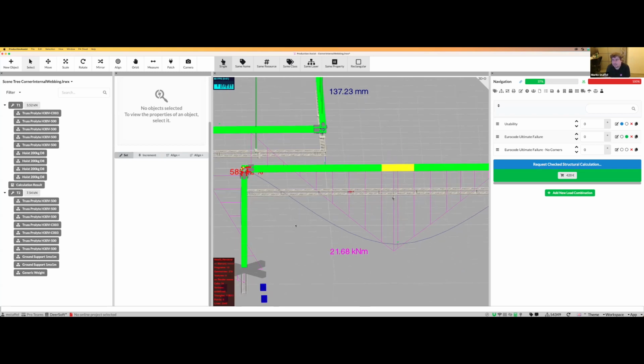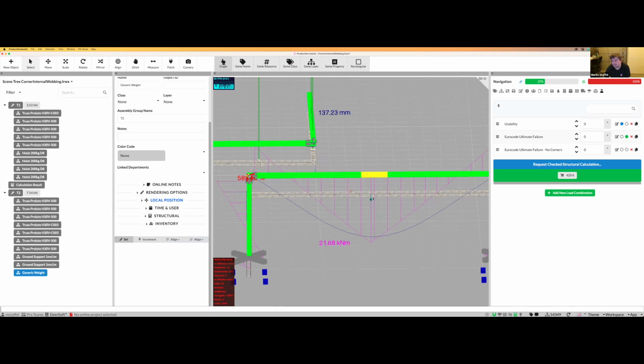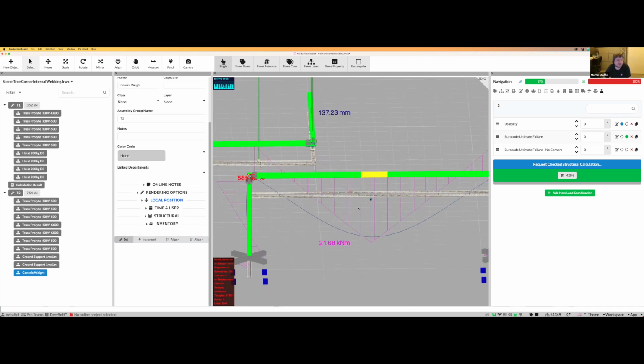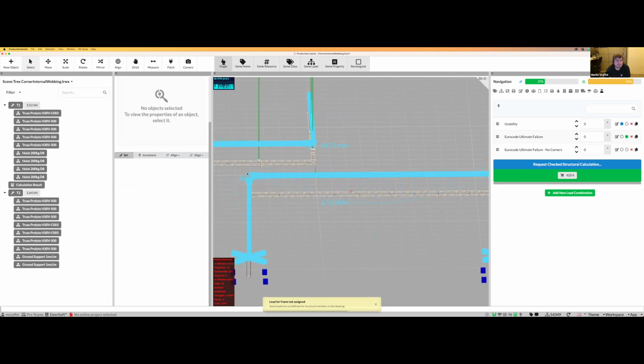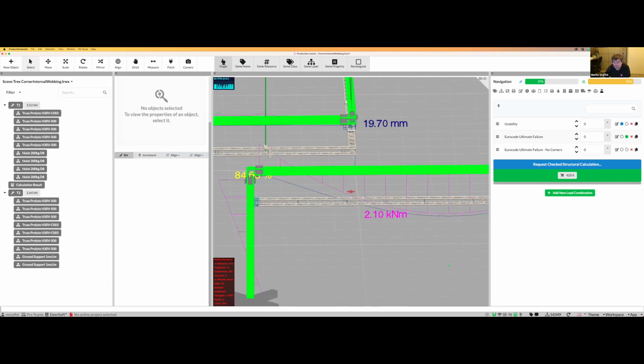There's one thing to say about this kind of calculation. It is a little bit rigged. We have a really long span width and a really big force in the middle, so that's why it's this overloaded. But even if I delete this middle load, we're still at 84% workload. So there is not much capacity in here.